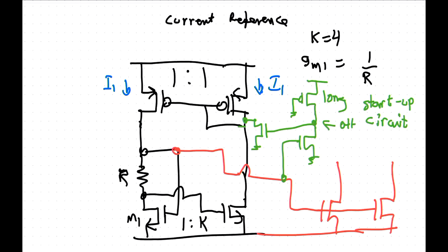Because after this, you have floated the output stage. The output doesn't matter because you have gain from the input to the output. If you design your op amp properly, then the dominating noise source is your differential pair. If that's not the case, you have not done it correctly. Normally, for signal to noise ratio, you want the amplifier input stage noise as small as possible. That's right. So you put in gain as soon as you can. Then when you have gain, the noise becomes less of a problem in the later stages.